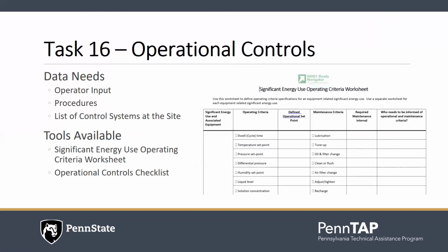Next, you'll have some control systems. Kind of think of them as machines, but an easy example is an occupancy sensor. There's not actually a person going through and touching that light. The occupancy sensor is doing all the controlling of the light. You might also have this within your compressed air system, that the compressors are taking a look for pressure in the system, and they'll turn on and off as it needs it.